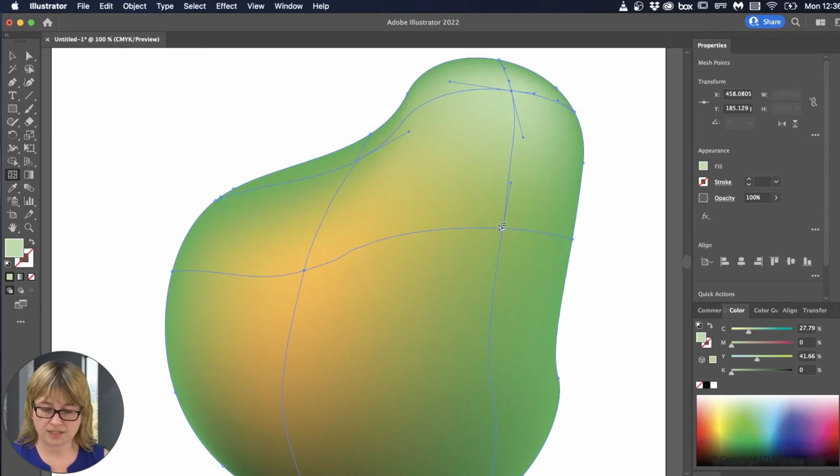You could click on somewhere on the line, any of the lines. You get a little plus. And so what it'll do is it'll place a point right in here. Now it does bring another curve through our shape, but it did not add any more vertical lines. It only added a horizontal line. You can do the same thing. You can choose a horizontal line and tap on it, and it will draw a vertical line through it, but it won't create any new horizontal lines. However you do it is fine, so that it's behaving with intent and doing what you're expecting it to do.